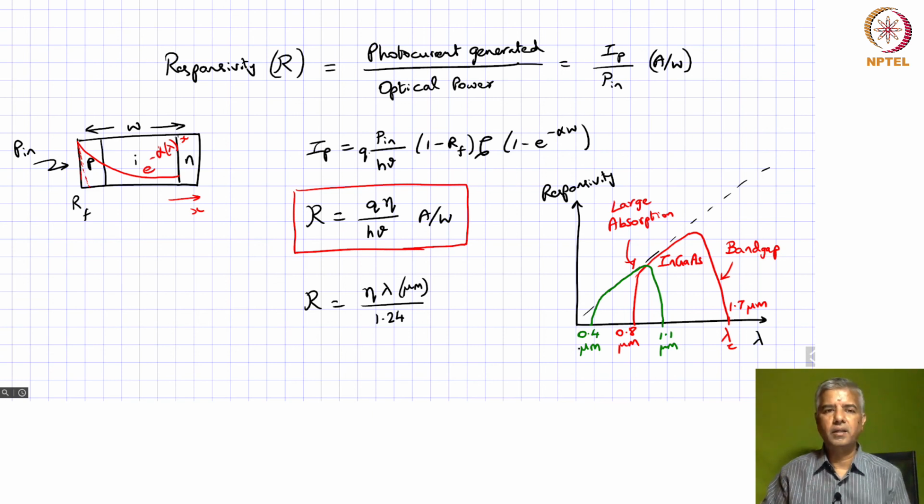Okay, and so it has very good responsivity over here, but very poor responsivity for longer wavelengths, because if you make this entire PIN structure relatively thin, then most of the longer wavelength light is going to just go straight through, so it's not going to register a lot of photocurrent within this structure. Okay, so those are the typical characteristics of PIN photodiodes.